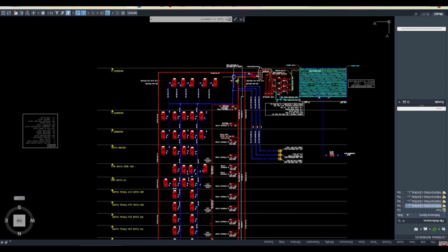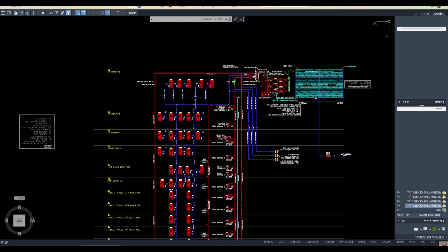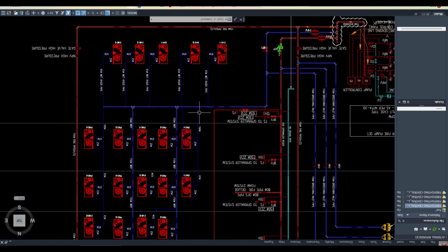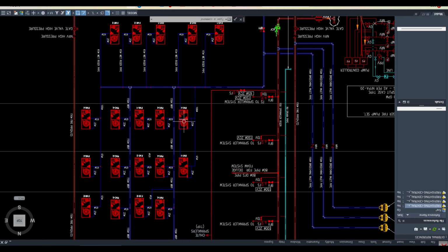I'm just speaking about the standpipe system, where water is available in the system, but the firefighting has to be done manually. And the sprinkler system is an automatic system. The sprinkler system is not manual, a person does not have to be there, but to operate the standpipe system, a person has to be present. So this is for manual operation.